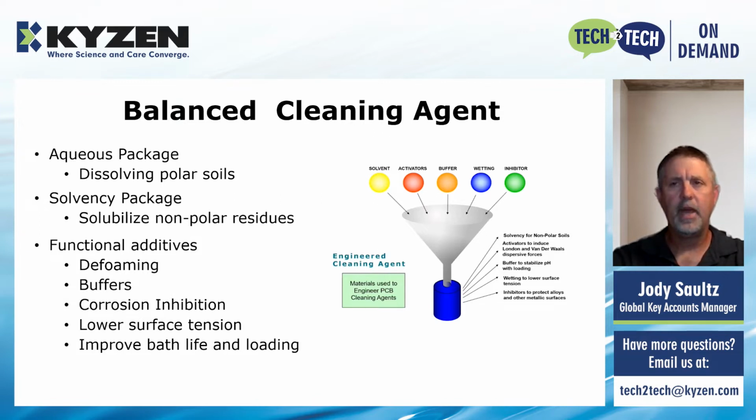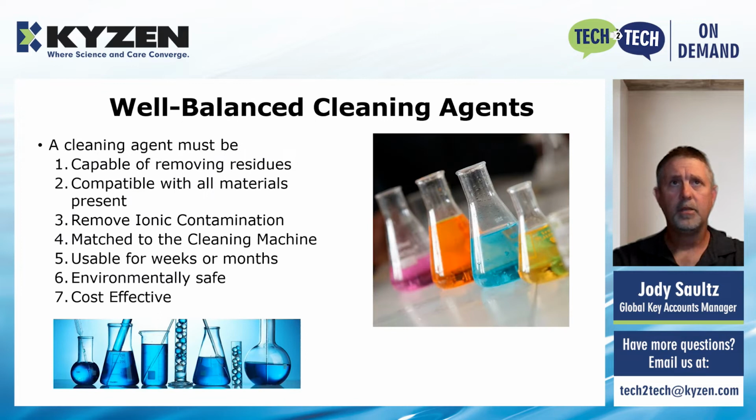Functional additives are included, such as defoamers in this balanced cleaning agent. There's buffers to help stabilize pH. There's corrosion inhibition. These balanced cleaning agents lower surface tension, and they're also going to give you some improved bath life and loading over the period of the life of the bath. So well-balanced cleaning agents need to be able to remove these residues.